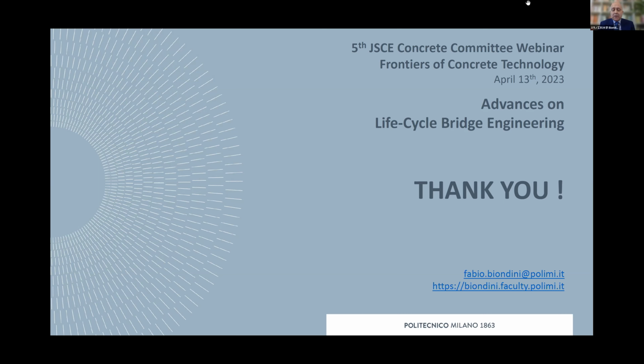If you refer to the experimental campaign I have shown, a large campaign of non-destructive tests has been developed and is currently under development, and they include sclerometric test, pachymeter test, ultrasonic test to characterize the mechanical properties of concrete, and we also made electrochemical test for corrosion characterization.